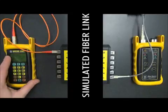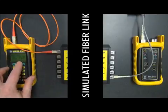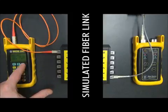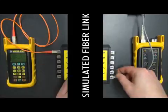And you'll see that we have our readings on the screen here. We have our link name, we have our fiber name, and we have our wavelengths, dB loss, and our pass-fail results. So if we're satisfied with this particular test result, we can press F3 for save. Now, as you can see, the number has auto-incremented here to the number 2. This means that we're going to connect into fiber number 2 and store that reading. But what I'm going to do here is speed up this process a little bit.